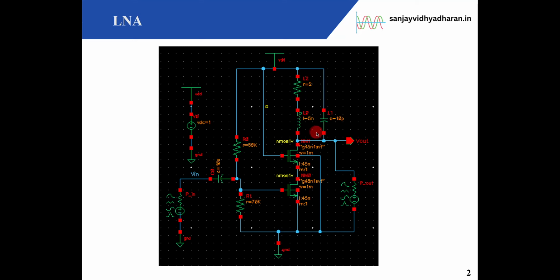Okay, so there should be some selectivity of frequency, and here I am using a tank circuit. An LC tank circuit will allow me to select the desired frequency. I have put a resistance here because any spiral inductor implemented in a VLSI chip will have some series resistance. So just to make it a bit more realistic, I have put this resistance. We may want to add a higher value of resistance if we want to increase the Q. If you refer to my first lecture on LC tank circuit, you will get more idea about this. So this is the tank circuit for selectivity.